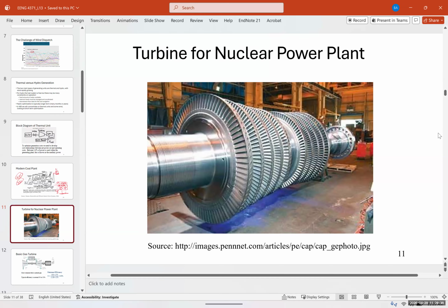And so for these reasons, in the context of economic dispatch, nuclear units are typically treated as must-run units, what we call. They operate at their maximum output, with their output simply subtracted from the total load before the dispatch problem is solved for the remaining generators. So we have that as base load, and we solve it for the rest of it.